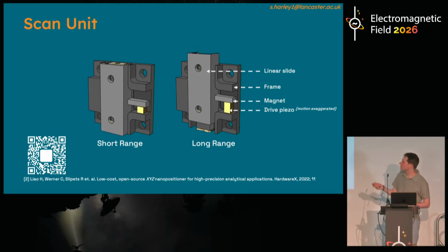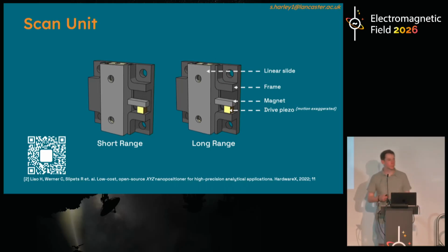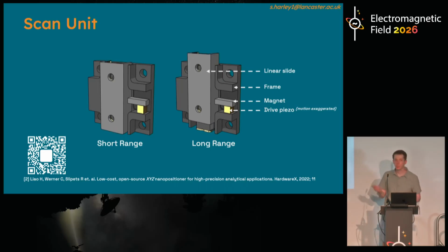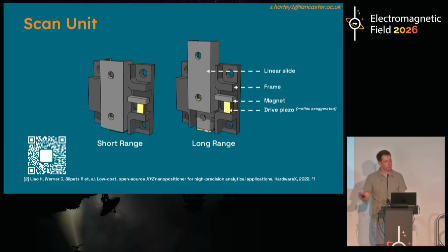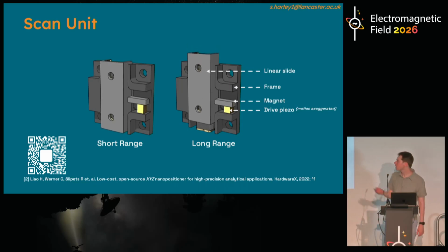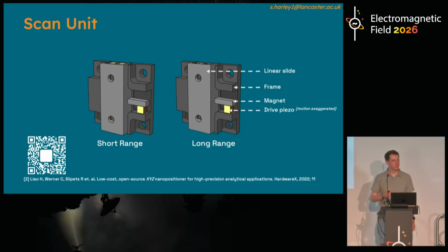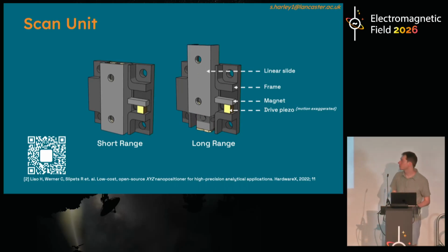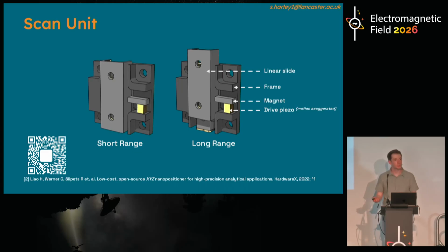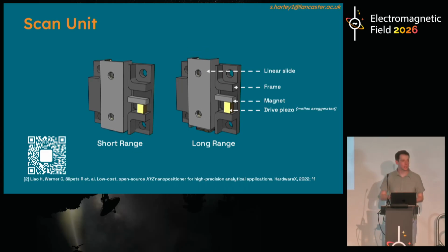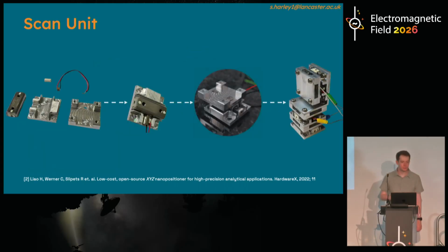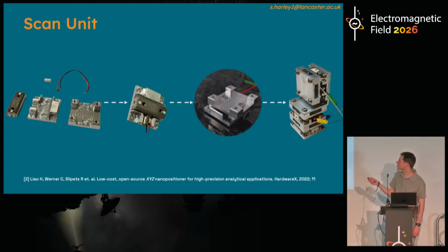And it's coupled to this linear slide with a magnet. So at slow speeds, that coupling is rigid, and the linear slide reproduces the atomic scale movement of the crystal. But if you move quickly in one direction and then slowly in the other, when you're moving quickly, the magnet will slip a little bit. So you actually get a net displacement, and you can move the stage in these kinds of steps to get longer range motion. So this is how that looks in real life.